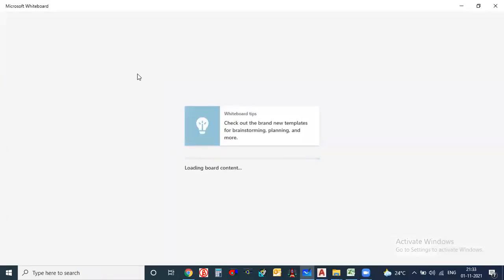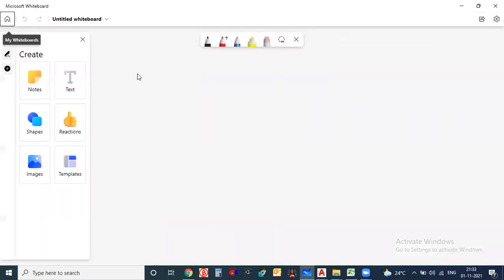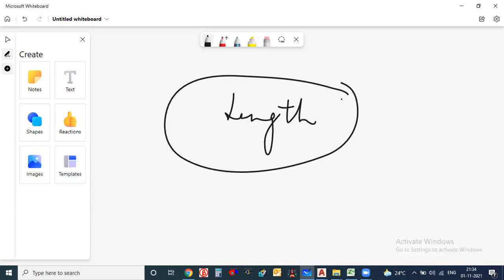Before making this sheet, first we should do the sprinkler spacing. That drafting work has to be done, and only after the drafting work do we enter into the Allied software. Because if you have not done any placement work, as a design engineer you don't have to go to the system and do the work. You can place the sprinklers, if you are very good at drawing, in one sheet. You can also connect with the node system. Or it's better to connect in AutoCAD, because in AutoCAD you will get the accurate length, and the most important thing is the length. We require the accurate length.